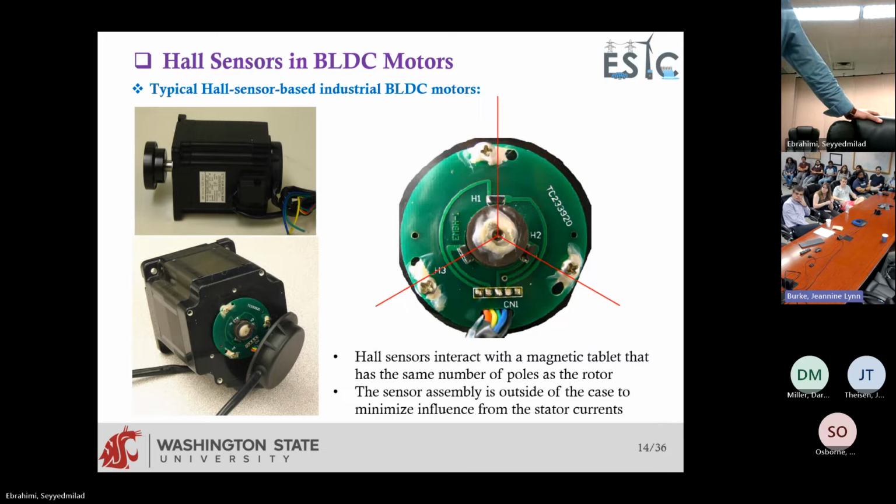But I understand, because we were doing a project where these magnetic tablets were not glued correctly, we had a lot of trouble because we had a lot of torque ripple and we had to adjust these magnetic tablets. But yes, there is no guarantee that you can basically do it. Then you have to look for other options, either resolvers or you go brushless control, sensorless control. Sensorless. Yeah.